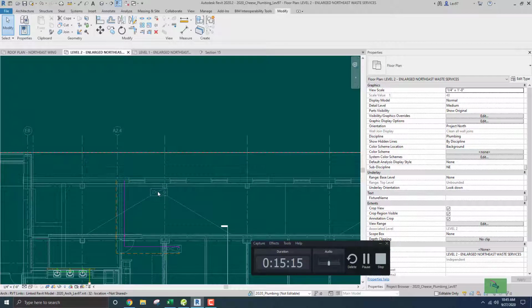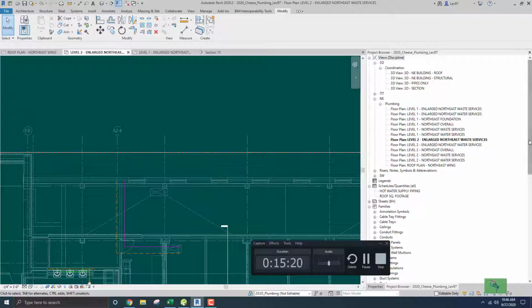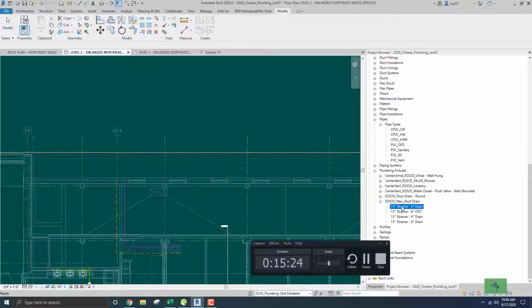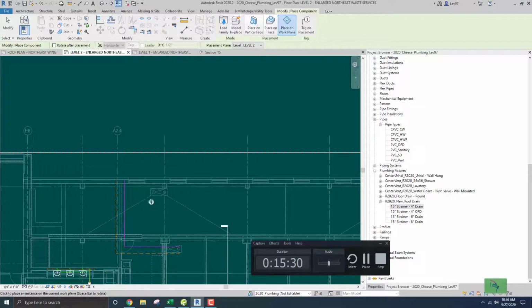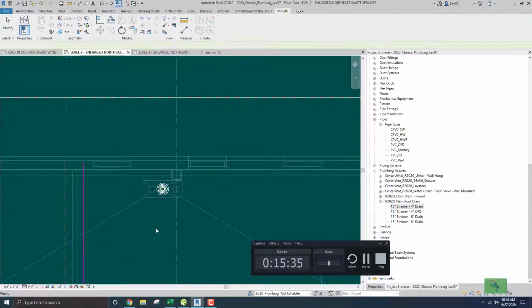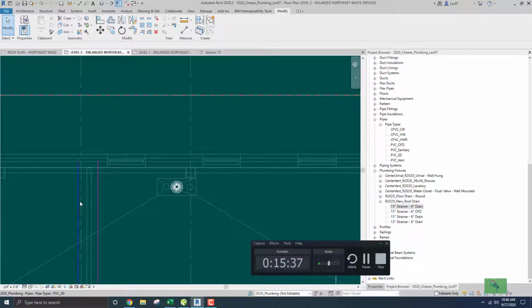There's going to be a set of, let's go and get this storm drain. Let's just put the storm drain on there. So there's going to be another drain here. I'm going to put that on a work plane, which is here. Okay. And I'm going to connect this storm drain to that storm drain. And once we do that, then we will populate.